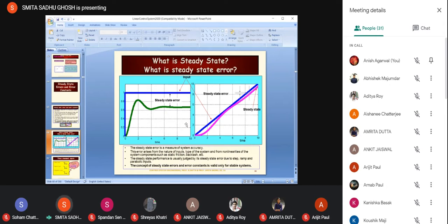It is not going to be only a proportional change, a scaling, say a halving or a doubling, corresponding to each point in time. I would not be seeing the same or similar response only with the scale factor coming into force. What I would see for a nonlinear system is that if the nonlinear portion has been reached, the nature of the response is going to change altogether, only because the value of the amplitude of my input has changed.